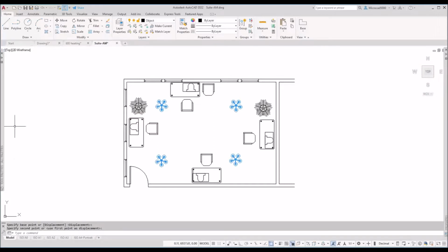So watch, if I say, no, I don't really want those. If I go into the erase command, it says select objects down the command line. If I hit the letter P for previous selection set, so letter P, hit enter, it picks those previous objects. And then I can erase them just like that. So I didn't need to go around and have that complicated selection set again. I just type in P for previous and it picks up your previous selection set. Okay.